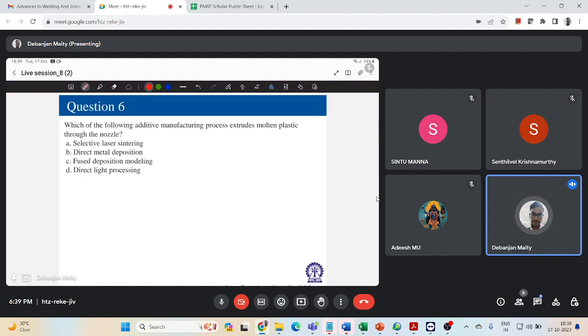And then finally you'll have this short circuiting phase where your arc voltage will be zero, your wire is given a backdrawing force, and at that point of time some kind of liquid fracture occurs and this transfer of material into the weld pool happens.